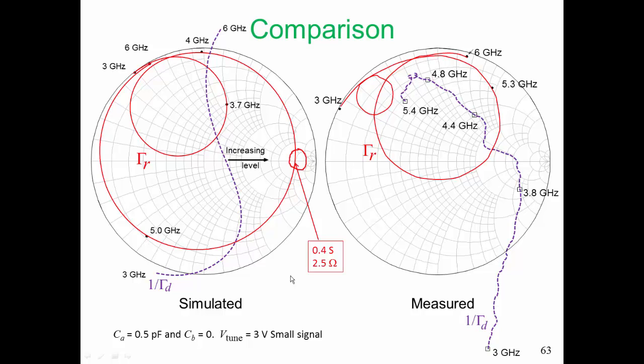Any resistance that we introduce when we're trying to do a measurement of our resonator is going to have a significant effect on the resonator. So my interpretation of what we're seeing is that the resonance is more likely to have the shape that we see on the left-hand side, the simulated shape. And what we're seeing on the right-hand side, to me, looks as though we have just a little bit more loss. We're kind of killing the Q of our resonator network. But the basic characteristic is there.